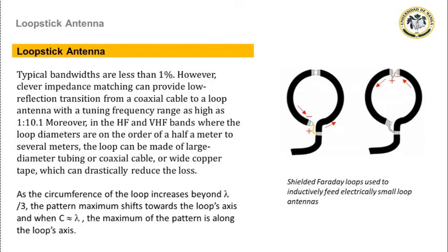Loop antennas consist of a loop of wire. Loop antennas interact directly with the magnetic field of the radio wave, rather than its electric field, making them relatively insensitive to electric noise within about a quarter wavelength of the antenna. There are essentially two broad categories of loop antennas: large loops or full wave loops, and small loops.